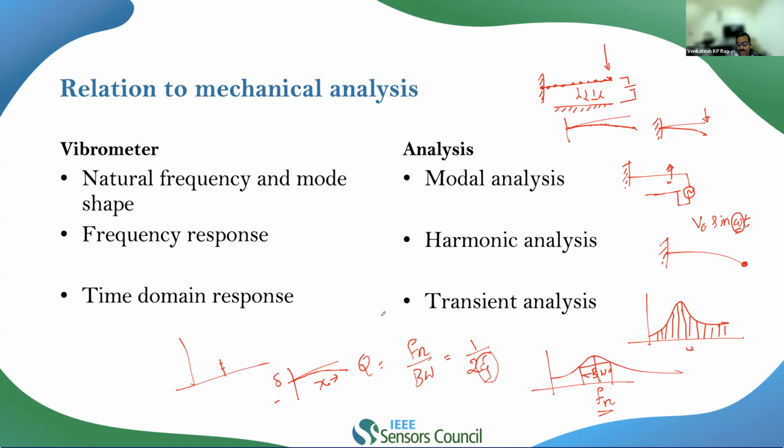So whenever you do the analysis with the laser Doppler vibrometer, you can extract the natural frequencies and mode shapes quite easily. I think there was even a demonstration in COMSOL Multiphysics also. We can always do this quite easily using any of the analysis software, the modal analysis. If you compare the readings you get with your LDV against any of the analysis software, doing the modal analysis is like extracting the natural frequencies and the mode shapes, right?